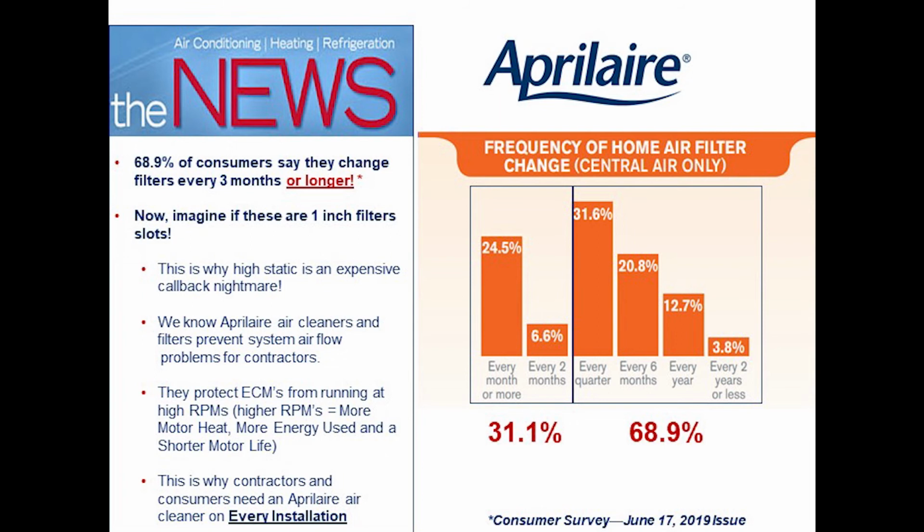And we know all the impacts of that. The higher the static pressure, you get higher airflow noise, reduced airflow, which is going to affect throw, especially to those distant rooms. It's also going to affect your ability to heat and cool the home, just period. Your heat exchanger can get hotter and your coil can get colder.